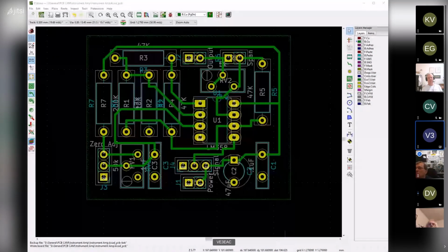And you use KiCad to then feed into the GRBL editor and into the 3018 CNC? That's the next stage. I still have to go in and change the pad sizes. The pads that are in there work just great when you're having a fabricated board, because a plated through hole is functionally more like a rivet, and on a single-sided board you don't have that.